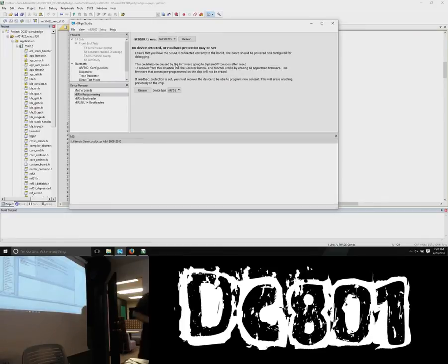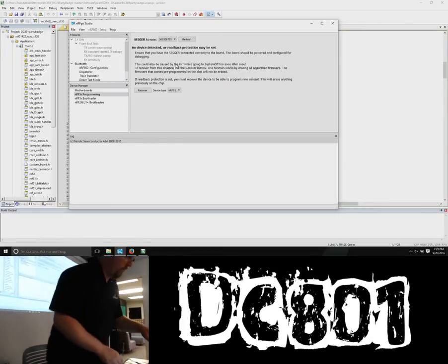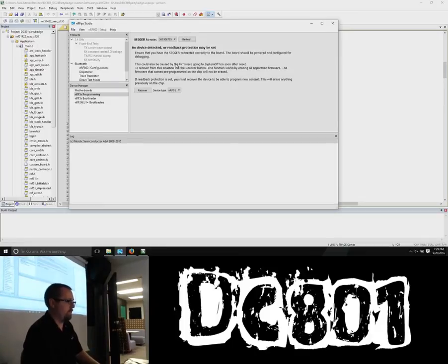So on the nRF Go, you need to make sure that you're on this nRF5x programming right there. If you're on any of the other ones, it won't show right. I see. You want to be there. So let me just reset this one.